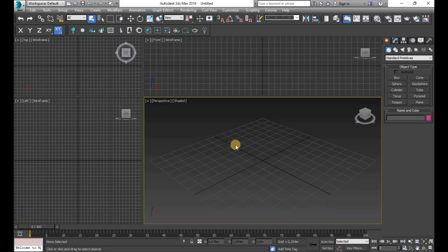You can modify the size of the viewports by dragging the intersection of the viewports on the splitter bars. To restore the original layout, right-click on the intersection of the dividing lines. A shortcut menu will be displayed as shown in the figure. Choose the Reset Layouts option from the shortcut menu. The viewports will be restored to their default size.